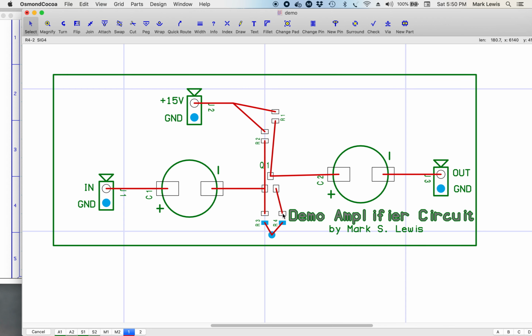These little contact surfaces on the top of the circuit board are pads. The lines are called tracks or traces. I used to say traces; some people call them tracks. Most of these are surface mount parts, with the exception of the connectors, the through hole parts. As I was saying before, through hole means the part has metal pins that go through the entire circuit board, top to bottom, whereas surface mount parts just sit on the top of the circuit board.